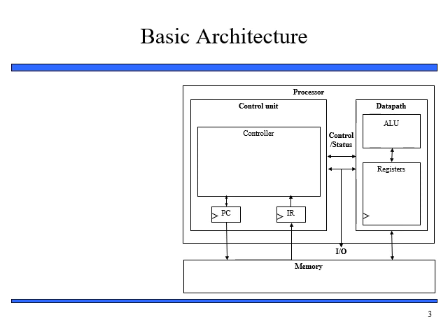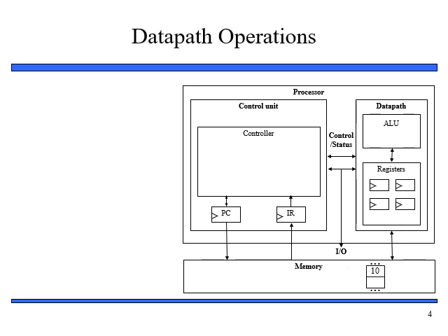Now, their operations are performed in data path as you can see in this slide. Now, you can see in this slide that multiple operations are performed in data path. For example, starting with the load. Load function read memory location into register in which contents are 10. So you can see the load will read the contents from the memory location in which the contents are 10, and it will load these contents to register.